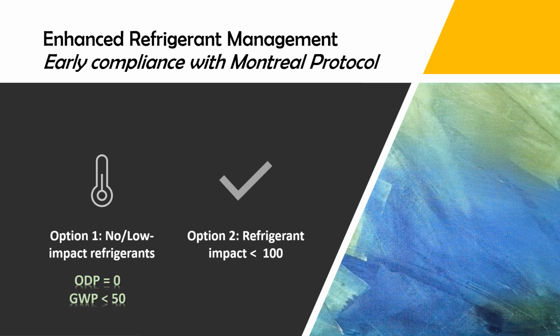Option 2 is to calculate your refrigerant impact to ensure that it is less than 100 and implement a refrigerant management plan that addresses leak detection, system retrofit, and an end-of-life disposal for all HVAC&R systems. You will calculate the life cycle global warming potential plus the ozone depletion potential times 10^5 and ensure that that is less than 100. You can get 1 point for implementing that option.